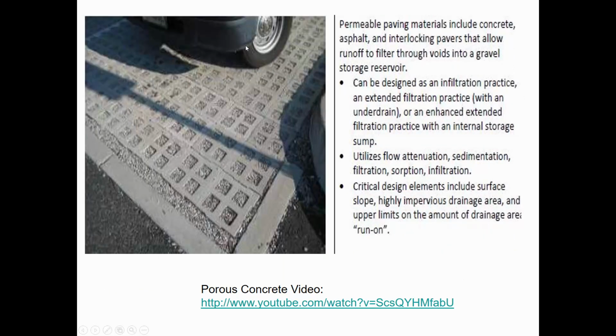So here's another one. Trying to make it so that concrete absorbs more water than it ordinarily would. And so one approach is to use concrete pavers and packing gravel in, where it used to just be a continuously impervious surface. Now you've got a little bit of impervious surface with the paver, like this might be a cinder block that you then reinforce with gravel. And so there's going to be better infiltration there than there would just be for pure concrete.